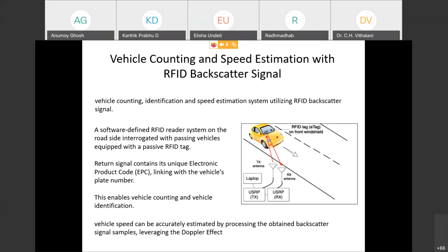Okay, so the first thing is speed estimation. That is very important. And over here, as you know, for vehicle management we generally use the range of 2.4 to 5.8 gigahertz. Since it is a gigahertz range, as I've told you, it will be working in the far field region. So the tag which will be read, it will be the backscattered signal, not the induced field. Okay, so you see, there is a transmitting antenna and a receiving antenna.